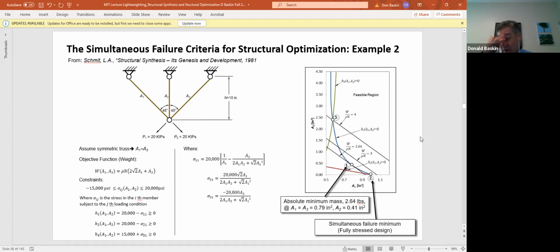So there's something interesting about this design. If you take a lot of engineers and say to them, okay, how can I make this thing as light as possible? They're going to say, oh, well, just figure out the stress in each one of those beams and then go to the minimum cross section that supports that stress. And maybe, in the real world, you put on some type of safety factor for anything that's not understood, or defects in the material, or some screw up in the supply procurement department. Okay, and that should give you the lightest solution.